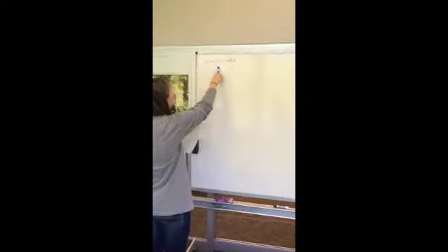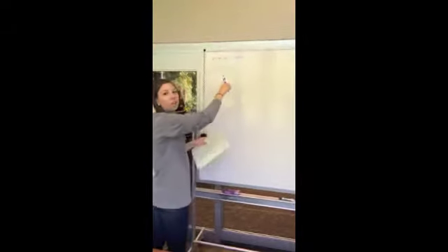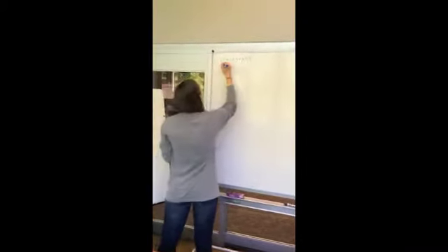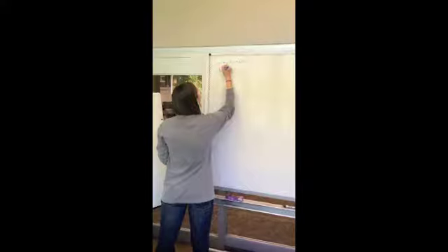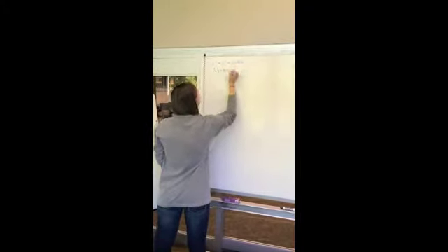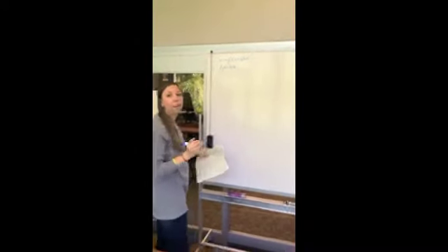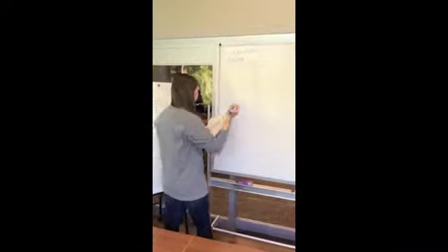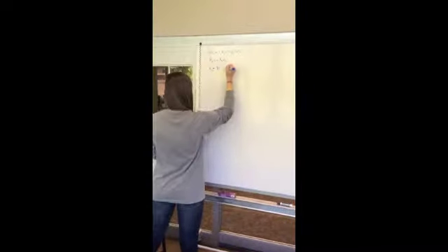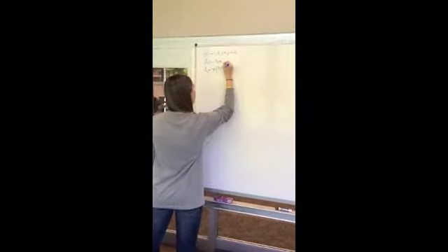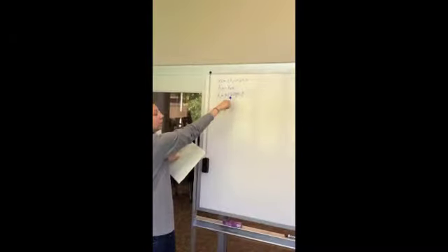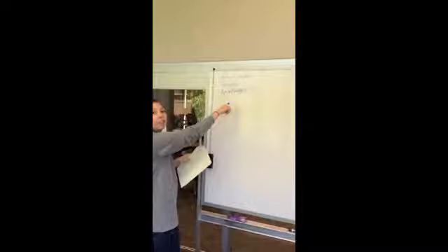And in this equation, the density 1 and density 2 are equal to each other. So therefore, this will simplify to A1 V1 equals A2 V2. I will start out by finding each area. So area 1. This is our diameter. We divide that by 2 to get the radius.